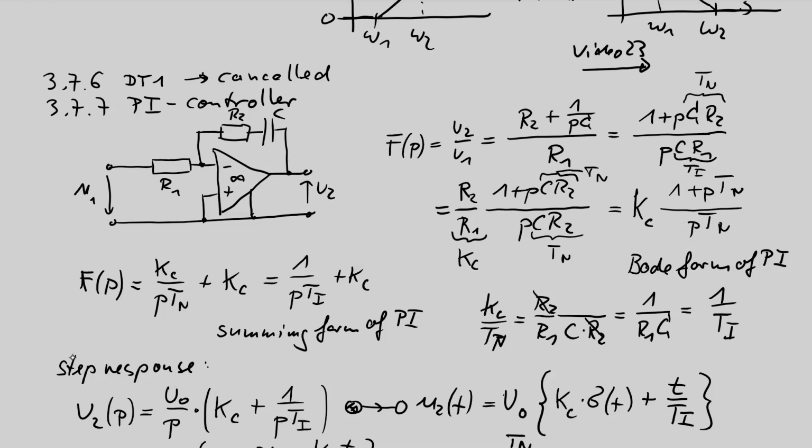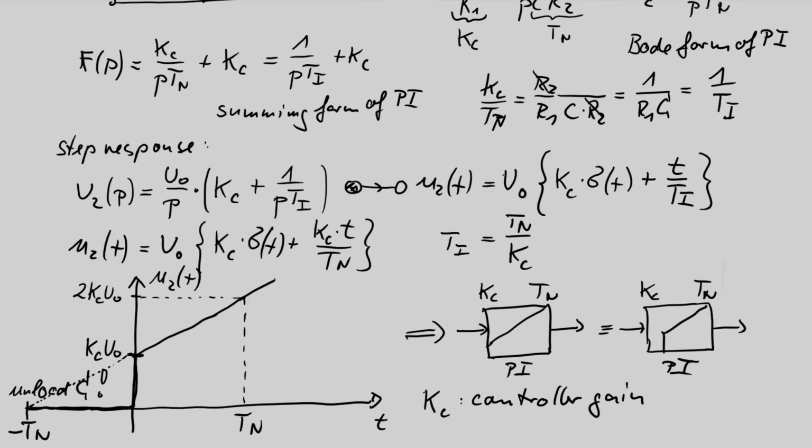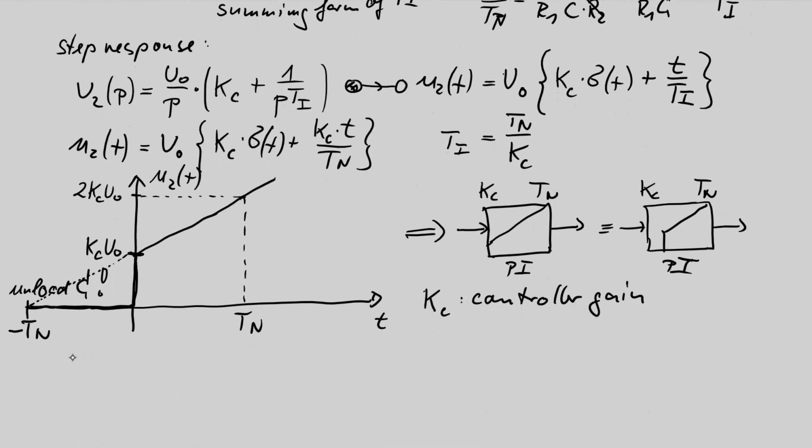The frequency value of 0 is the DC gain, DC for direct current, for constant values; a battery has DC voltage. If P is 0, you see the numerator is not 0 but the denominator is 0, so this goes to infinity. So Kc cannot be the DC gain. The DC gain is infinity.